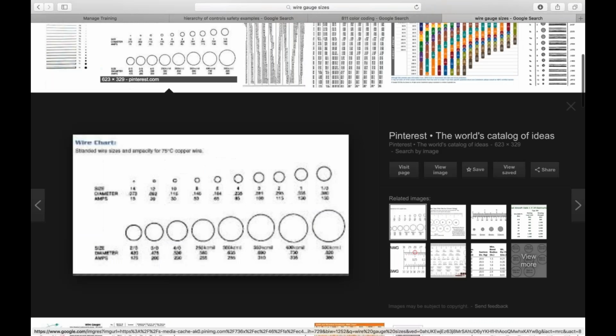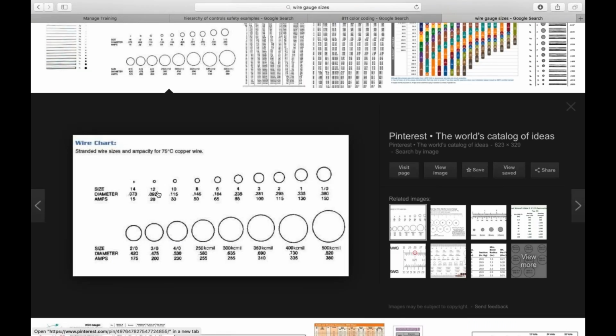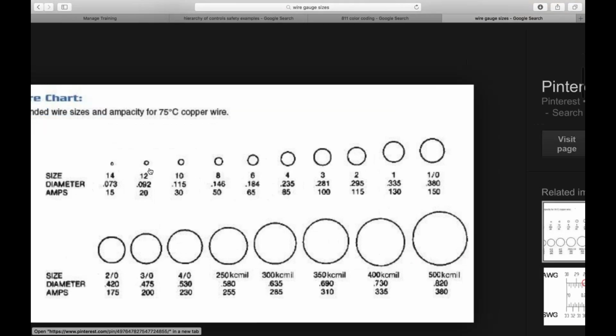Okay, and basically this is what I'm talking about, folks. Let's say in your home, normally you have a 12 or 14 gauge. 14 gauge in Louisiana, a lot of times is on our ceiling lights. All our receptacles and outlets in our home, and all our commercial plumbing, commercial electrical is a minimum of 12 gauge. Okay, so it's a little bit thicker, but the number goes down.